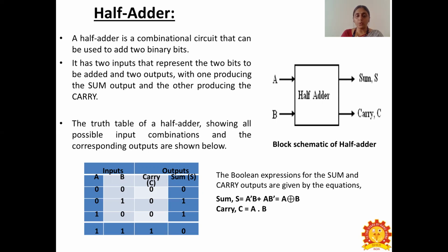And the corresponding Boolean expressions for the sum and the carry outputs are given here, which are stated like: sum S is equal to A' B plus A B', which is represented as A XOR B. And carry C is represented as the product of A and B.